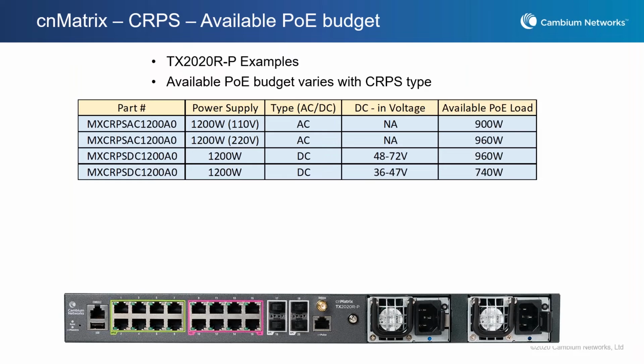So anyway, you can share this power across all the ports. Some 30-watt devices might only be pulling 10. So if you have eight of these 30-watt devices, that could be a maximum of 240, or it could be as little as 100. But anyway, the PoE power budget is what you have available at any instant in time. I'm going to highlight a couple here.